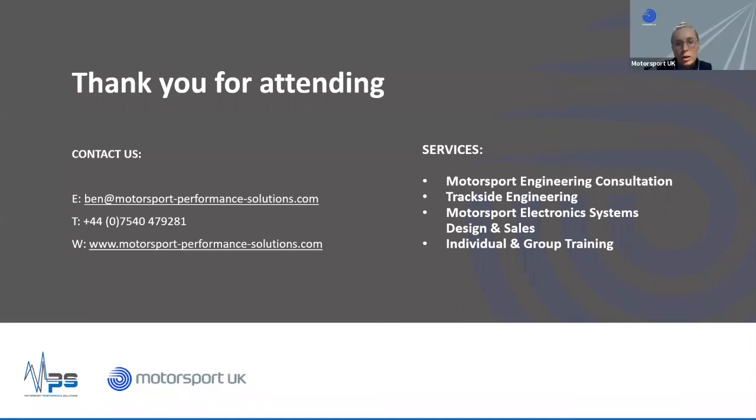Perfect. You may have answered this one in the braking section, so if you have, we'll move on. On monitoring brake pressure, would you use two sensors if you have separate brake cylinders for front and back? So again, yes. If your budget's there, that's what I do. All the professional customer cars do that.